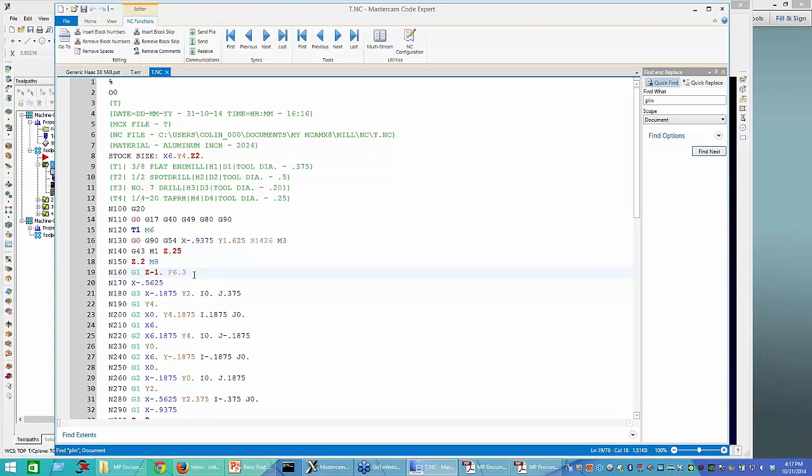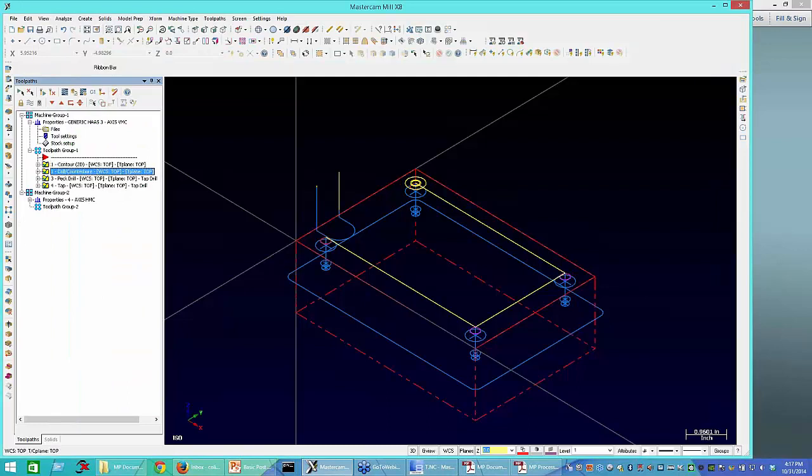Absolutely. Can I get the cutting time from the NCI MD and export it to the NC file? So it looks like a cycle time. The best option if you want to calculate cycle time is to use a .set file, because a .set file linearizes all of the output, and internally it turns off canned cycle output for drilling. So what that means is that the cycle is actually captured, so we can get more accurate times, and the secret is to integrate the output set file into your post processor. So we can actually have the post processor call up the .set file, pass it the NC file info, calculate a bunch of values, and then pull those values. But that's not something we can do in a minute.